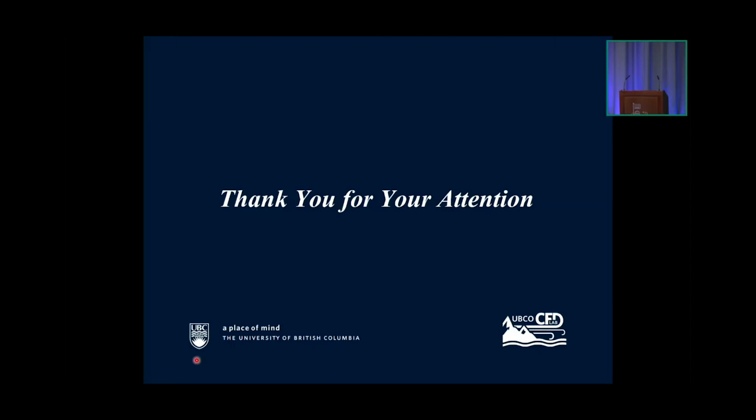The LES provided the why. Now we have a pretty good sense of the BEM being very, very fast, giving the answer in seconds, and it's physically explainable in the context of the LES, which took about a year to do. That gives us some confidence in the BEM being a useful predictive tool, not something I would put onto a turbine without doing some wind tunnel experiments, but at least it gave us some direction as to why the BEM is giving the predictions that we saw.